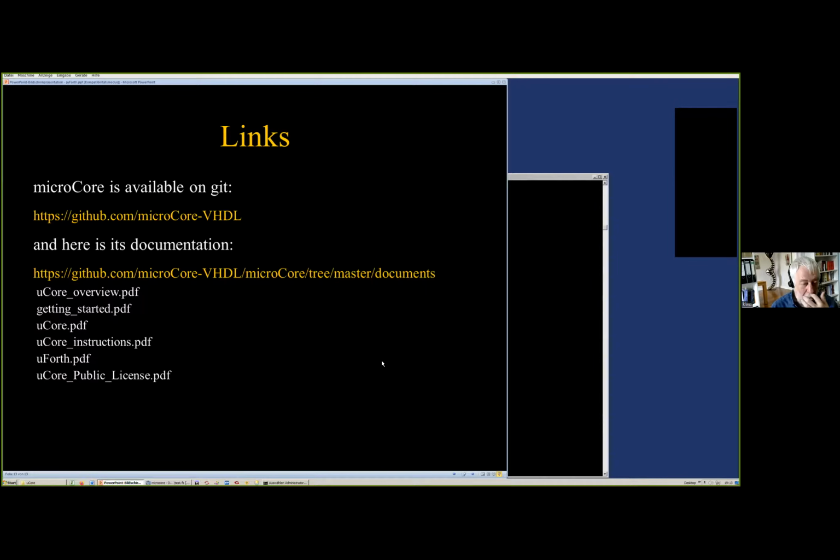Klaus, to turn it on its head, could you use a standard Lattice board with the FPGA on it and then a USB to TTL converter and two voltage regulators? I think that's how you described it.